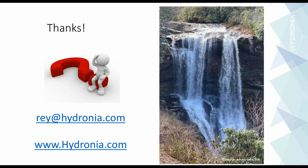You can model multiple dam breaks that occur at different times. If you were to use the initial conditions only, then the dams would fail at the same time. But if you use the dam breach component together with the initial conditions that represent the dam height and conditions, then you can set the dam breaches to start at different times.